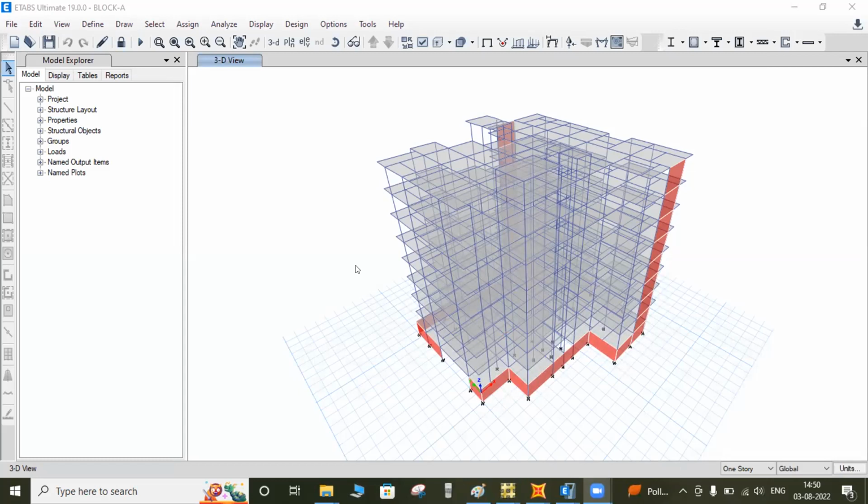First of all, we have checked the model for errors. Our model is free from errors, so we are moving to the modal analysis. Basically, we identify the stiffness of our structure. Our mode 1 and mode 2 should become pure translational modes.